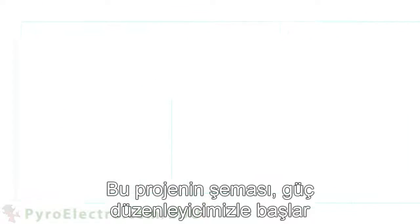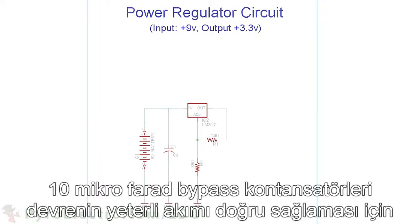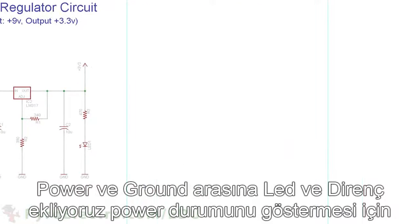The schematic for this project starts out with our power regulator, which uses a 9-volt battery input to an LM317 with two resistors that set its output to plus 3.3 volts. Two 10 microfarad bypass capacitors make sure the circuit has enough current to operate. We'll also add a resistor and LED from power to ground to notify that power is good.